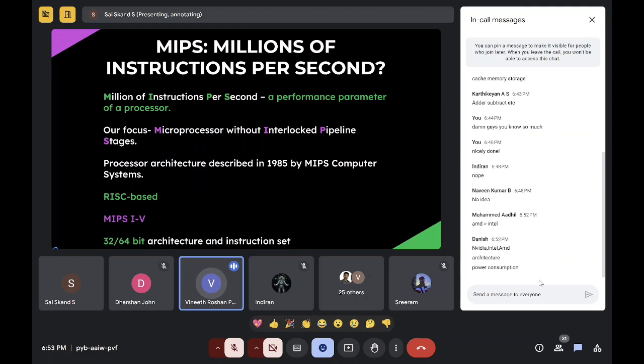So what might be done in CISC will take a lot. It'll be a little bit more complex in RISC. But what you get in trade-off to this, even though you might not get the speed and the power, you get much smaller hardware because the instructions are smaller, your circuit is also smaller. And due to that, your power consumption is also smaller. That's why in your phones, you don't see x86 processors.